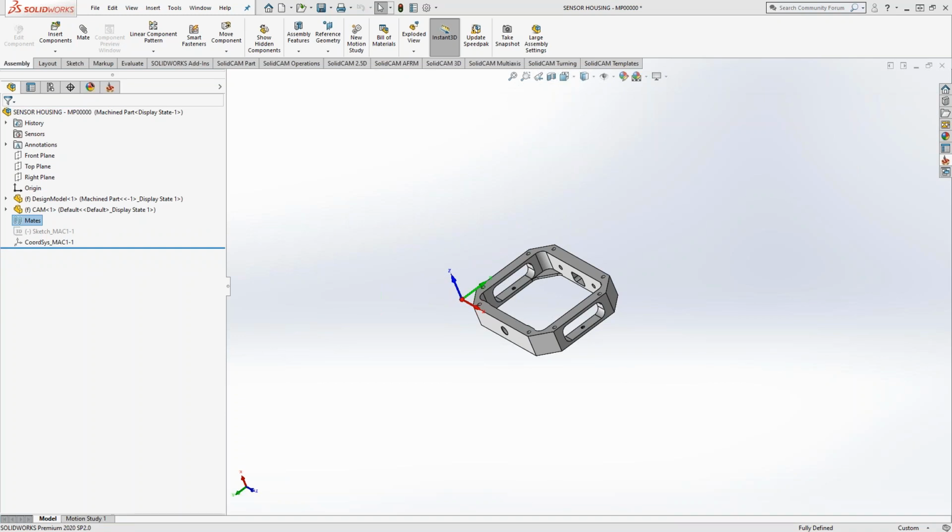But what I'm doing is I'm basically bringing in a SolidWorks assembly. So assembly inside of our otherwise assembly here. And basically all we're doing is we're going to mate it to our target. You'll notice in the left menu there, right next to the design model, there's a little F in brackets. That means that this solid, our target solid here, is stuck in space. It actually doesn't move. And if I try and move it, it says the component is fixed.